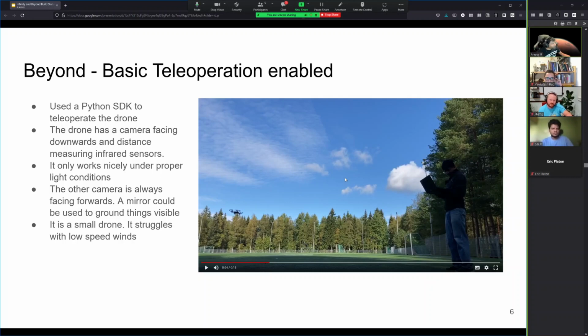I tried around 4 commands for this trial. The first command is take off. It takes off to around 1 meter, then move up 100 centimeters, move forward 200 centimeters, and then finally land. So it was quite easy. There are simple commands like move forward, and the parameters are in centimeters. I think it's a text-based, ASCII-based interface. The drone attaches to a specific IP, and then you could just send UDP packets to that IP in a specific format, and the drone would respond. That is what the SDK is doing.